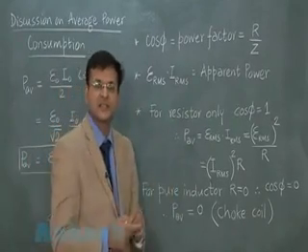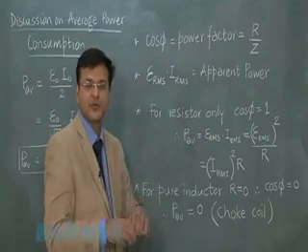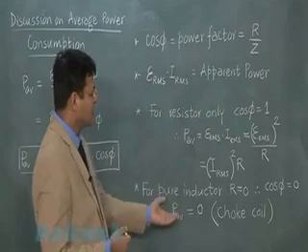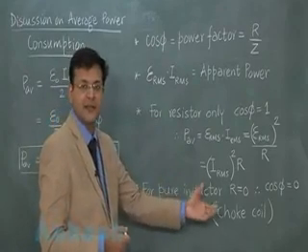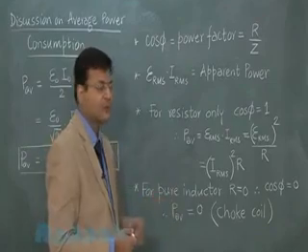The tube is working as a resistor, and along with that we add a choke coil so that the current is reduced without any power loss. This is the function of the choke coil, which is essentially based on the fact that its power factor is 0 and the average power consumption over the circuit is 0.